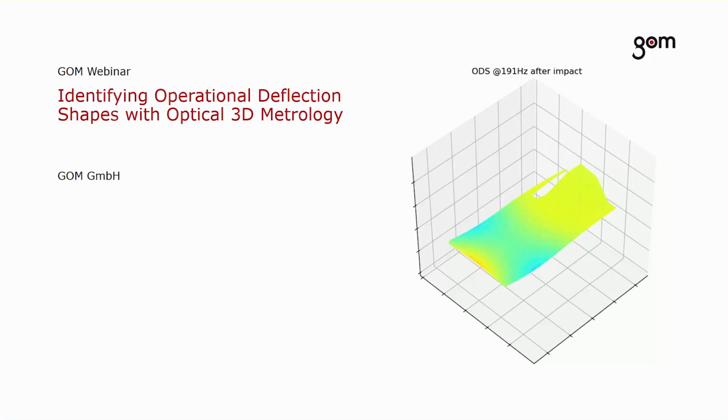So we see the actual measured response of the component, or in general the object under test, is what we can derive from Aramis. And we see this is the operational deflection shape. So we measure the component under a forced motion during a vibration analysis test, and we capture the amplitudes of the deflection on the structure. So we measure ODSs, and these can be used, of course, to compare to the simulated or calculated mode shapes, or to derive model parameters from these measurements.